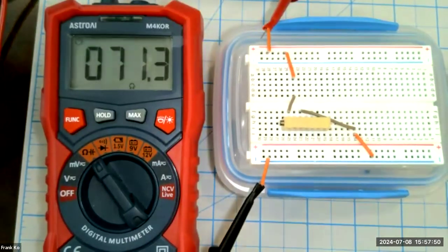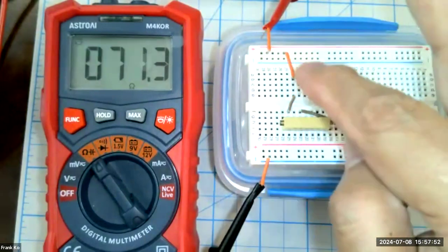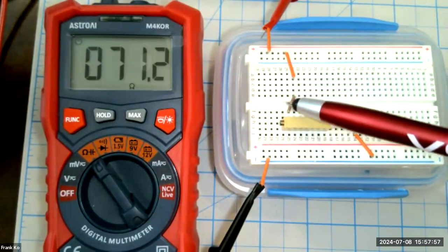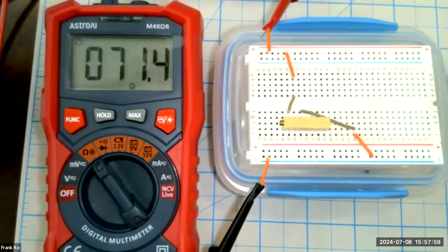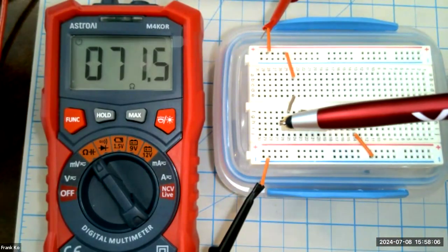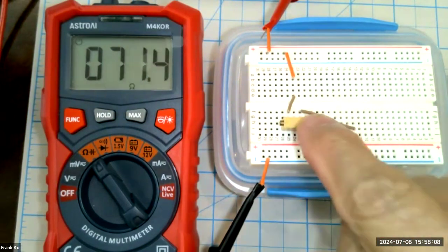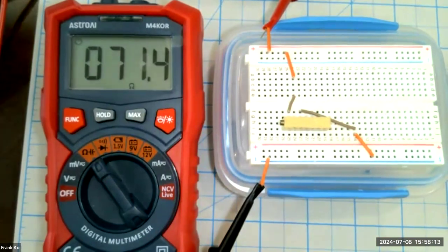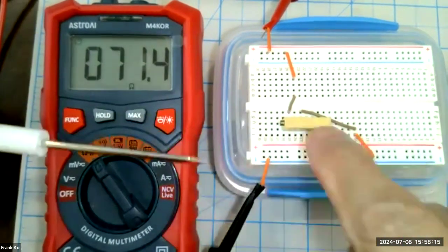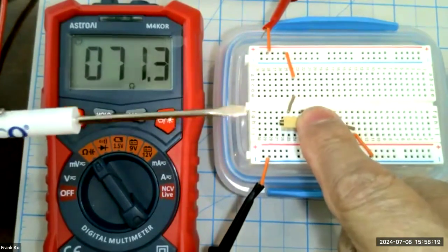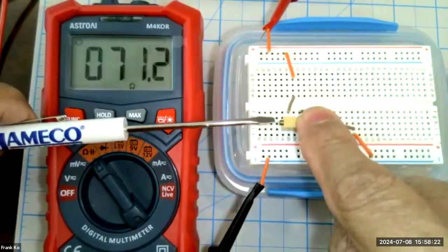Okay, so I've got my ohm meter connected to one side of the pot with my red mini hook to the very first pin. My black mini hook is connected to the blue rail, which is connected to the middle pin. So now I'm going to use the screwdriver and make an adjustment on the post. Right now, the ohm meter happens to show I've got 71.6. Now, when you use a screwdriver to make any adjustment on the board, I highly recommend you hold your component down and then bring your